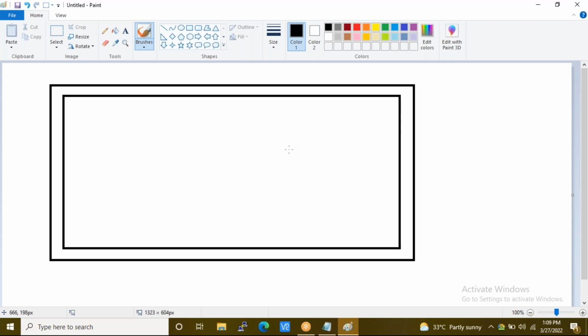Now this is where there is a small difference between analog design and physical design. When you talk about analog design, they will be designing for a specific gate level, let's say the transistor level. They will be majorly focused on stick diagram based implementation. But when it comes to PD, you will be using the cells developed by the analog team in your design.